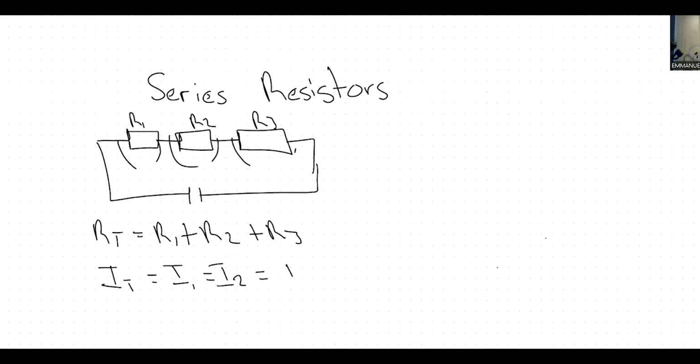So we're simply saying the current which flows in a series circuit is the same, but the voltage is not the same. Hence, here I can have V1, V2, and V3, and here VT, which is the supply voltage or the total voltage. So to find my VT, it will be V1 plus V2 plus V3.